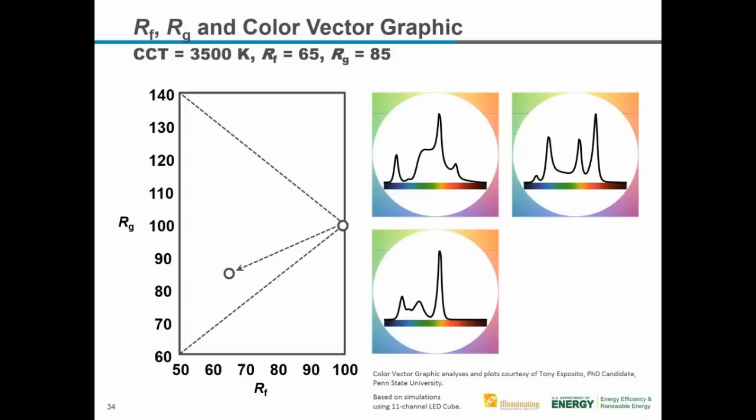These tools are a new way of communicating the color rendering performance of light sources. So in addition to being used by specifiers to evaluate light sources, the same tools can be used by a source manufacturer to engineer new sources with purposely designed spectra. In the past, there's been, I think, less of an incentive to do so because there was no clear way to communicate product performance. The new measures and graphics in TM-30 have the potential to encourage new and innovative products and perhaps new and innovative marketing of those products.